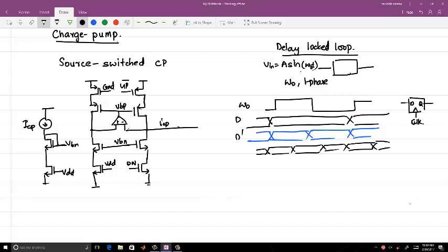You need more phases. Either you need more phases or you need a higher clock frequency. Okay, so both the things exist depending on which is the power efficient requirement. So you may need multiple phases to do this. This is one requirement: multi-phase clock requirement, clocks required in sub-rate clock and data recovery, you can say clock and data recovery.